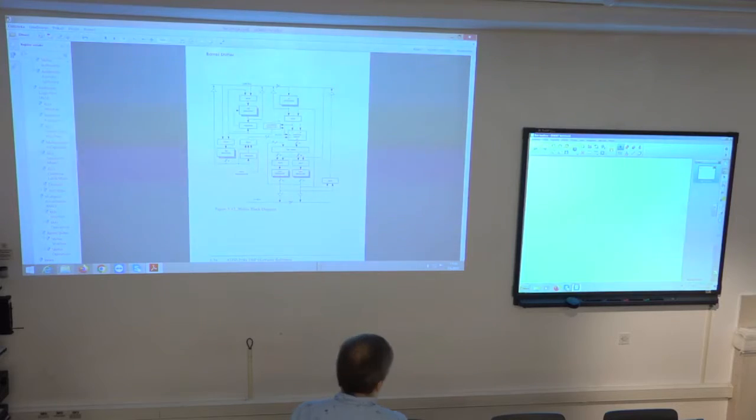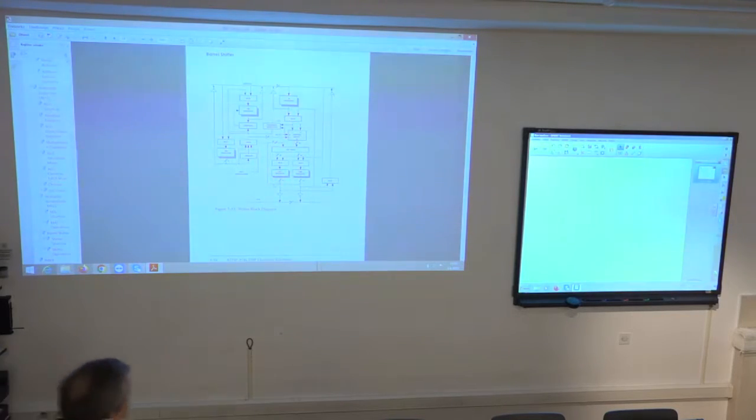It is the same architecture that I described last time. We have this 16-bit input register and a 32-bit output register that is composed of the upper word, shift register 1, and the lower word, shift register 0. Each of those is 16-bit. And we have this SE register, which can hold the value of how many positions I want to shift left or right.